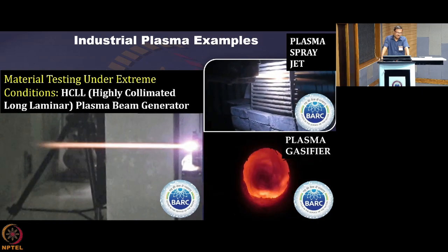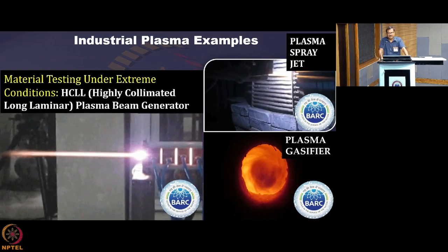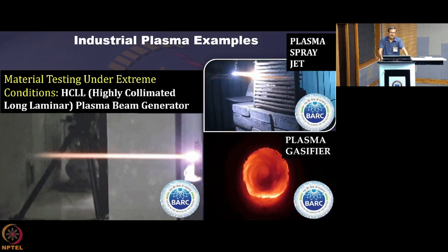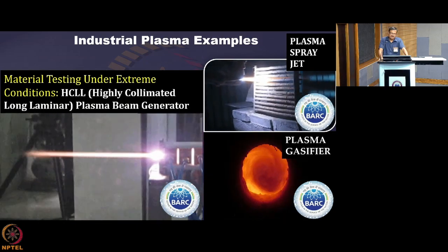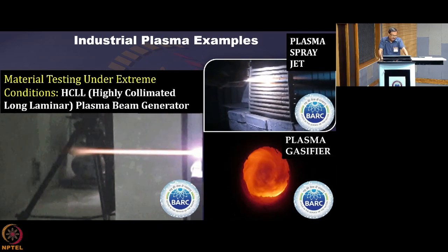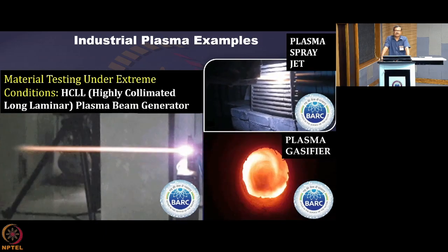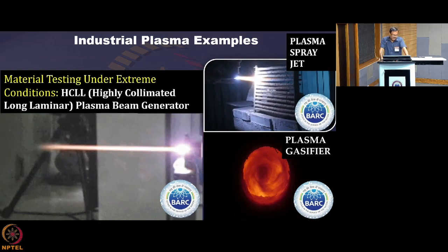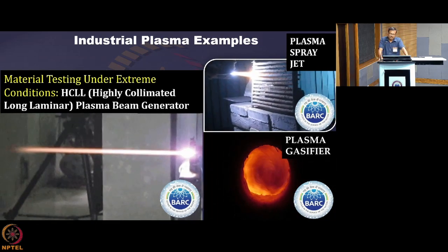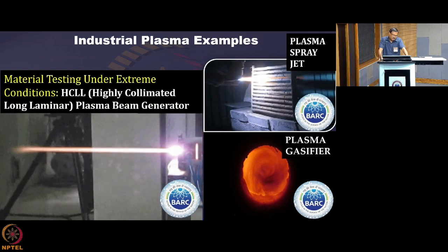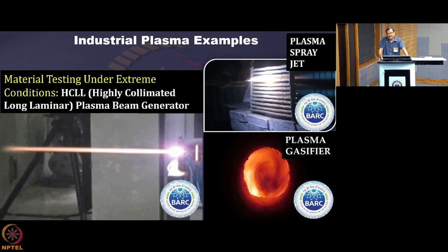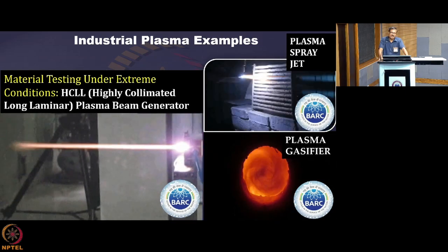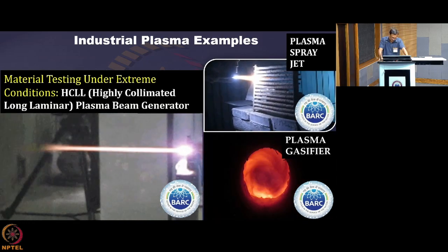We are using the torch to make the hazardous chemical mitigated. This one is PVC, polyvinyl chloride. So chlorinated plastic, if you burn it at a temperature of say around 400 to 600 degrees centigrade, which is a very common temperature you arrive at when you burn it in the open. When you do so, very carcinogenic compounds like dioxin and furan get generated at that temperature from this kind of material.